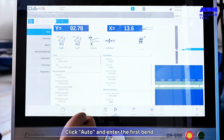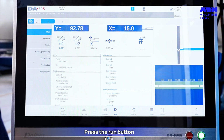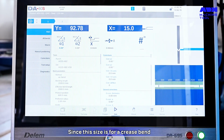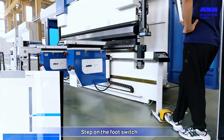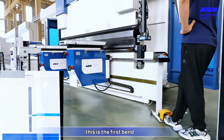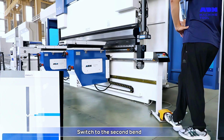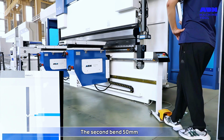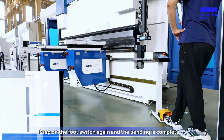Click Auto and enter the first bend. Press the Run button. Since this size is for a crease bend, it will run to the actual set value. Step on the foot switch. This is the first bend. Switch to the second bend. The second bend, 50 millimeters. Step on the foot switch again, and the bending is complete.